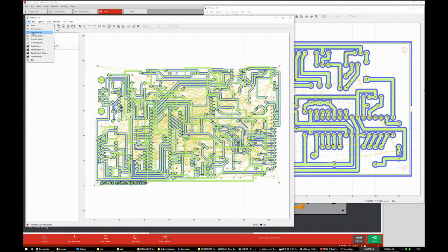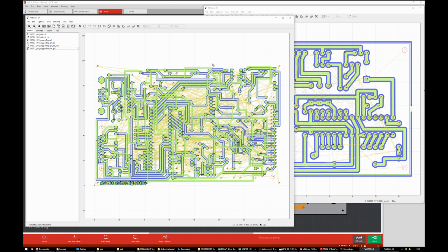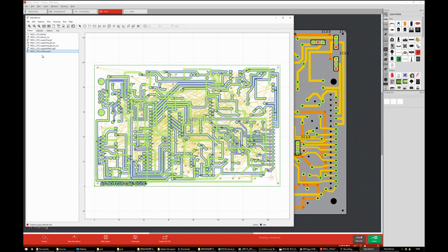So we open up another gerber, which is the cutout, which is what, contour? Yeah, it's the contour file. And the contour file is basically just the outline border of your board. Border of your board in Fritzing. Here we go. Where the light grey ends and dark grey starts. This is your cutout. I'm kind of going back on myself now. But basically, okay, let's return to cutting the copper, and we'll leave the contour to last.